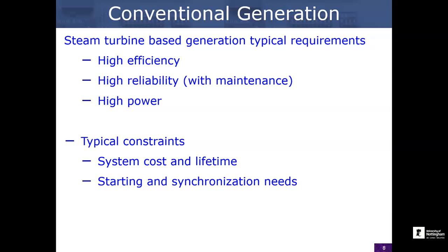They also have challenges around starting and synchronization needs. One of the big challenges around the grid is how we actually couple new power plants in. I talked before about how all of these power plants are running at exactly the same speed with the same frequency. And we do have some challenges of, if you want to connect a new generator to the grid, you have to connect it very carefully, or the whole thing will just tear itself apart and catch fire, trying to synchronize and absorb energy from the whole grid at once.